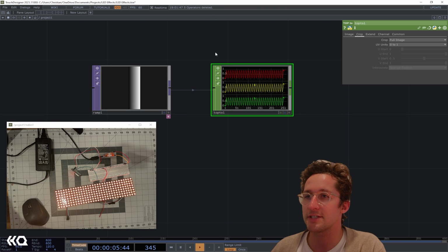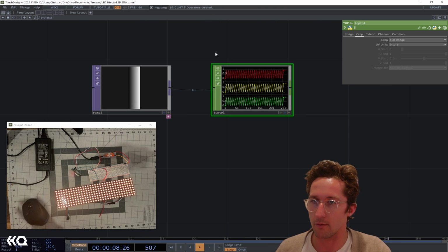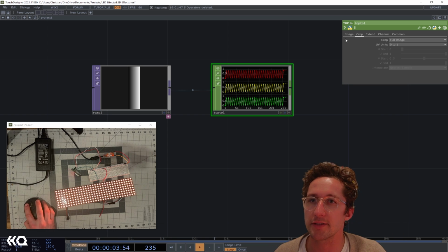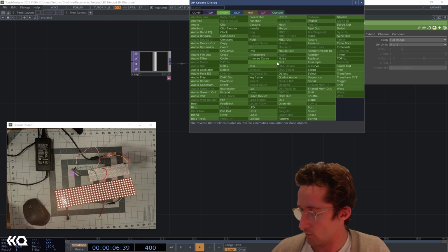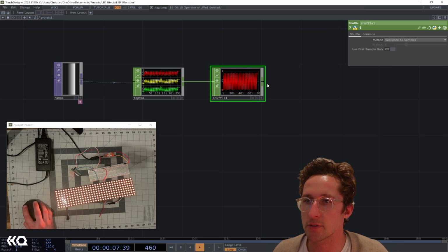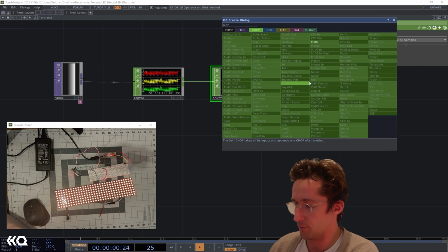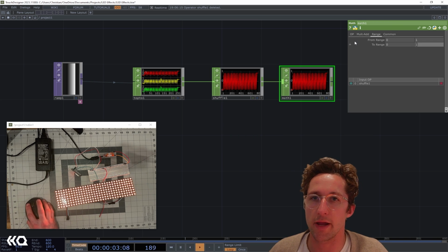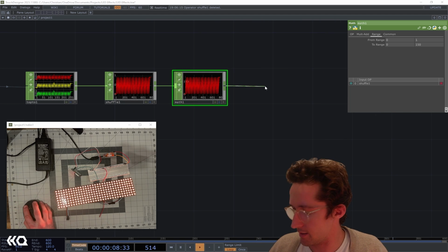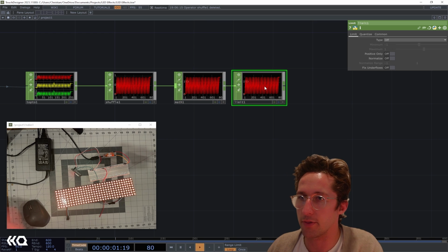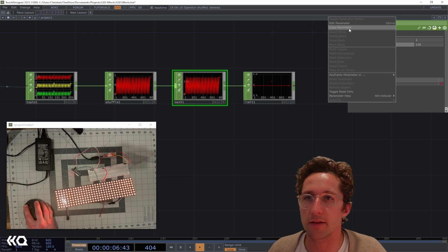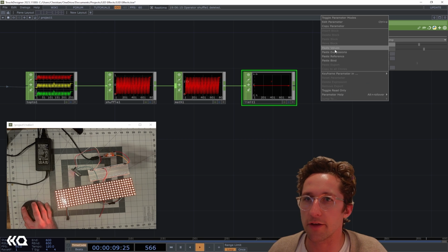In the previous setup, I fed that into a shuffle and had to kind of disentangle the CHOP data that I was getting in. This is a little bit of a faster solution for that. We're going to feed that into a shuffle, choose sequence all samples, and connect that to a math and set the range to, I don't want to blow out the LEDs, so let's just do 150. And just for the sake of sanity, I'm going to put that into a limit and clamp these values such that it's going to correspond to our range values.